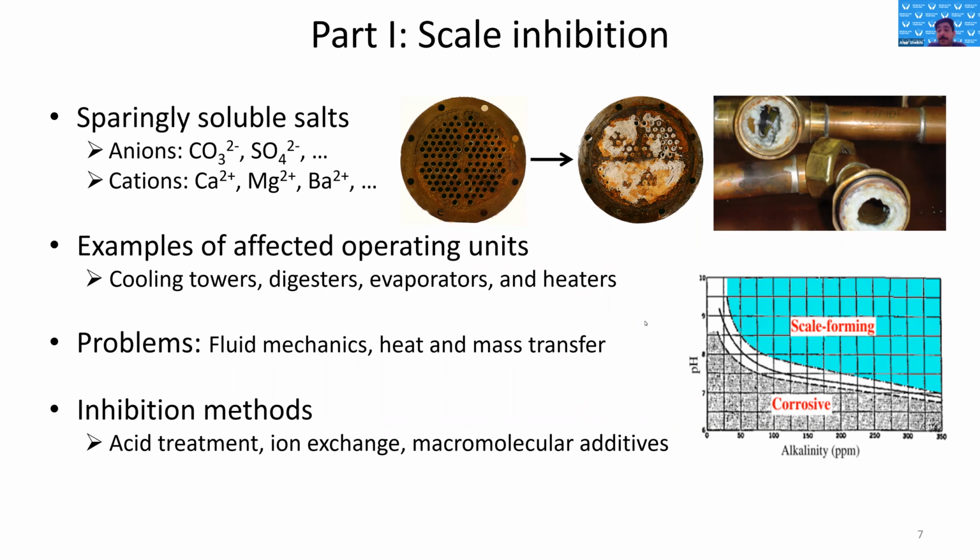One of the interesting applications that we were interested in the past years was scale inhibition. Scale is the sparingly soluble salts that form in water-based units, tend to adhere to the units, block the units, and increase the resistance against heat, mass, and momentum transfer.